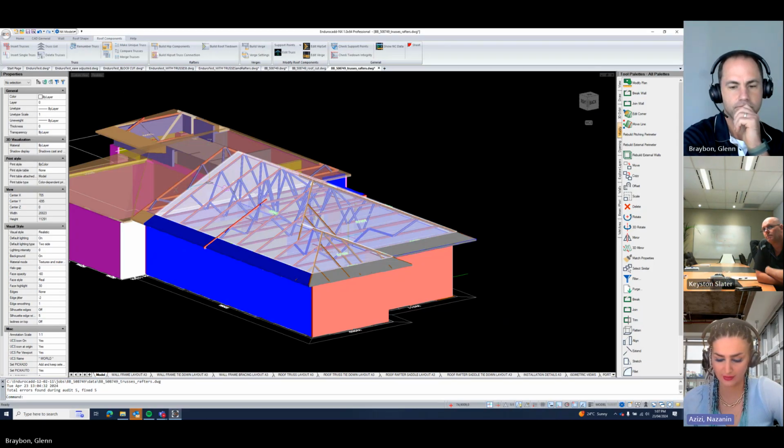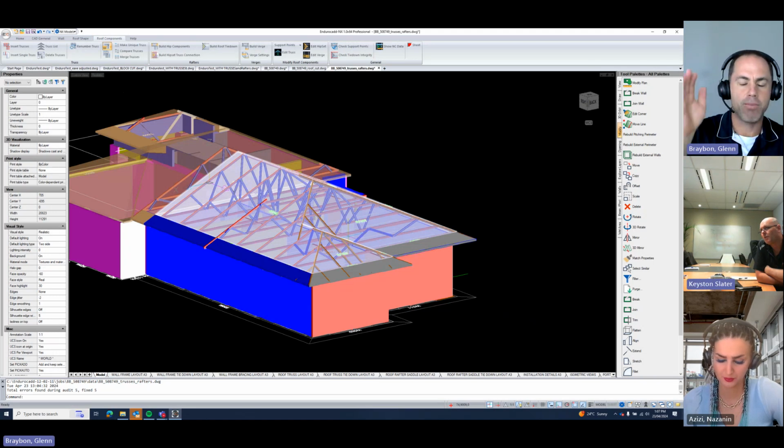I will double check this one. The dimensioning is wrong now. At the moment, it shows just a thickness. I think so. Because it's a double truss and it dimensions to the front face, there are two trusses and the front faces are 80 mil apart because they're kind of toes facing out. So it actually gives you an 80 mil dimension from the front face of the first of the double to the front face of the double.